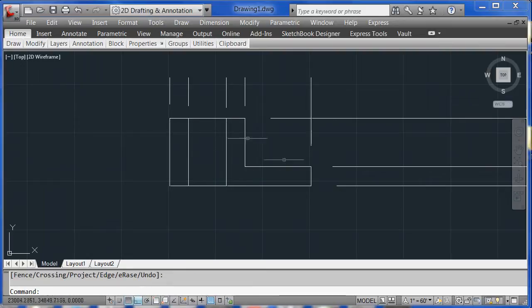So as you can see, my piece here looks very similar to the drawing on figure 6. I just need to now move over here and move to the right-hand side view. So what I'm going to do is go ahead and drop another vertical line, keeping the F8 orthogonal on. And now that I have these lines over here on this side of my construction line, I'm just going to go ahead and trim these off now.